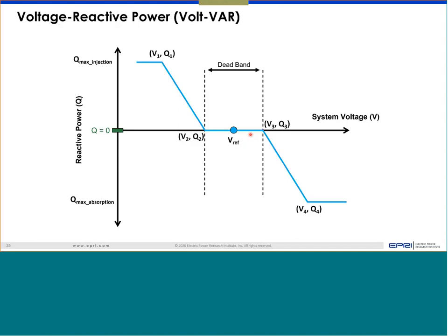is 0.98 and 1.02. So deadband is plus minus 2%. This one most probably goes 0.9 or even lower. So that tells you how you want to define this slope, how aggressive or benign you want to make this slope. And it will continue that. And slope can go, you can define it, say 0.8, just to reduce this slope.